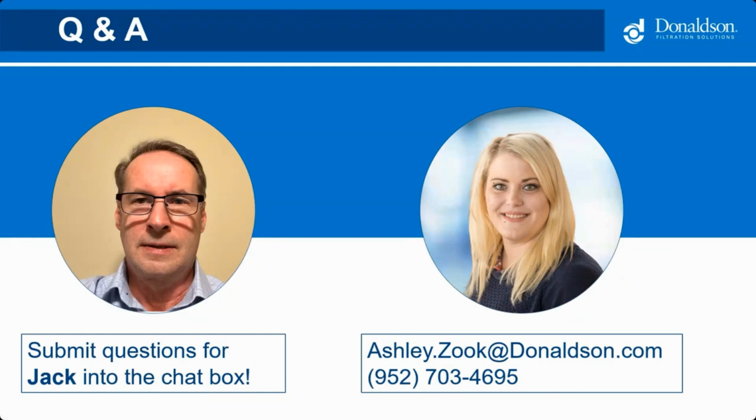All right, next one is, when is the air to media or air to cloth ratio not the correct parameter to use? If there is no filter media inside or being used, such as a cyclone. But for the most cases, if you're using a filter of any type, you should always consider air to media ratio or air to cloth or AMR. It's very important. And keep in mind that all applications and the type of media being used are different.